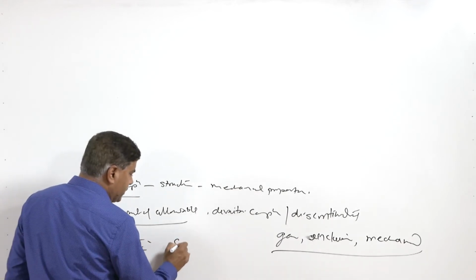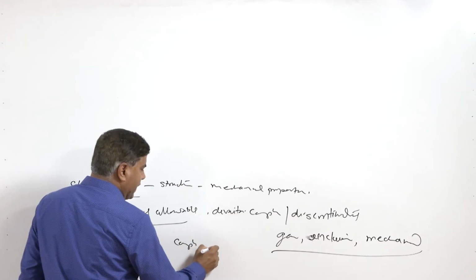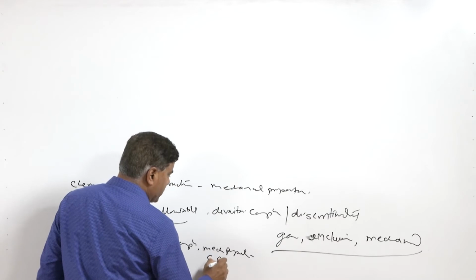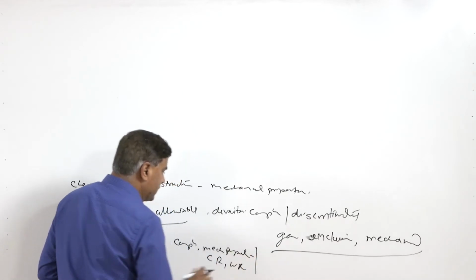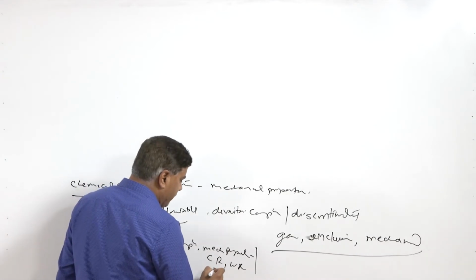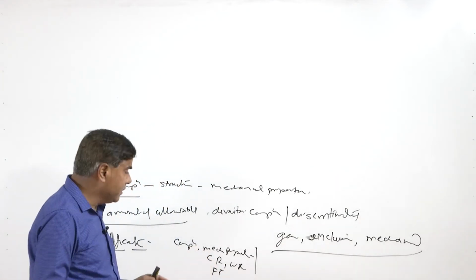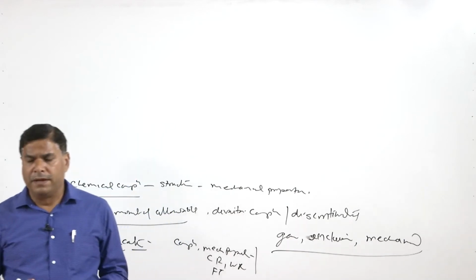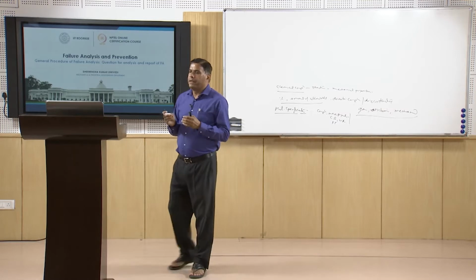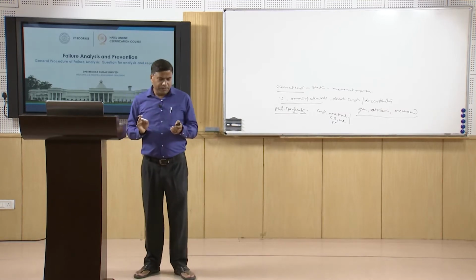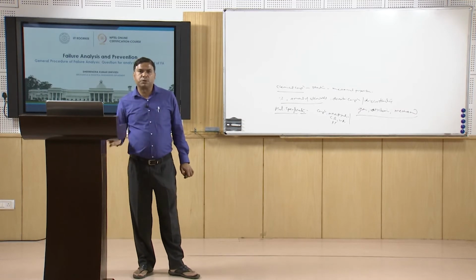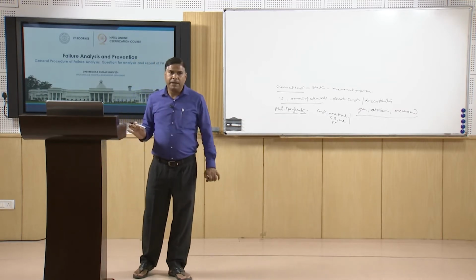This may be in terms of chemical composition, mechanical properties, and also in terms of corrosion resistance, wear resistance, as per the case. Whatever material has been chosen, did it have the required properties or not, and efforts are made to establish if the material specifications or properties used for making a particular component had any role in the failure.